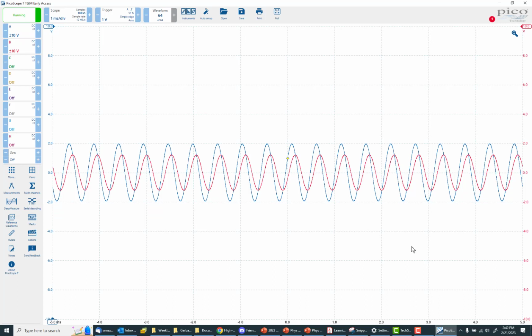And I'm looking at the voltage across the capacitor. When I look at the high-pass filter, I'm looking at the voltage across the resistor, right? Think of the voltage divider, and it's going to be on the opposite side. So basically, the easiest thing to do is go back and forth with the frequency, notice the behavior, notice the phase shift, and then think to yourself, okay, I expect zero phase shift when the capacitor is not having that much of an effect on the circuit.